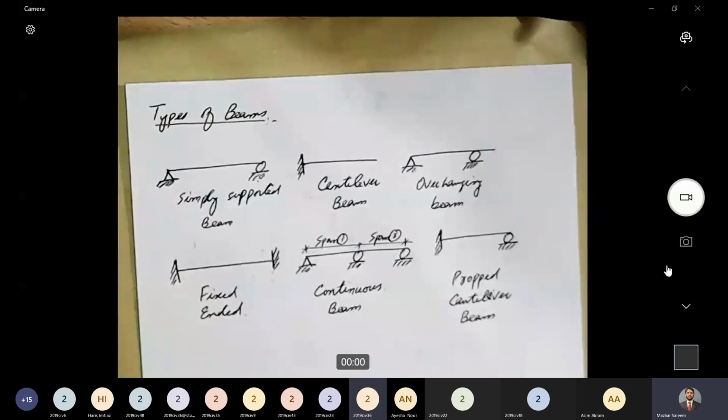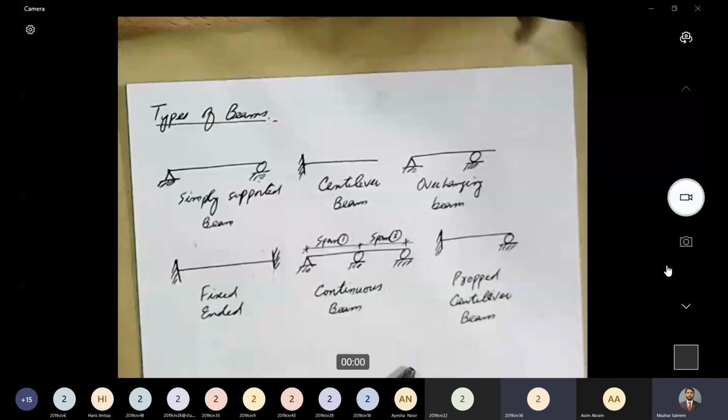36, you wanted to say something. Sir, this is what determinate means: if you can find the values of all the loads and reactions. Fine. Determinate beam. Okay. I see a hand raised. Please go ahead. Sir, if we talk about determinate structures, then for this structure, if we want to calculate all the reactions, we can apply equilibrium conditions, and these can be satisfied. But if we talk about indeterminate structures, then equilibrium equations cannot help us find out all the reactions for that specific structure. Yeah, that's right. That's right.